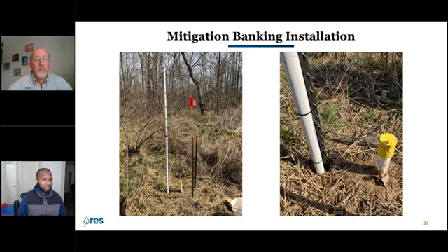So what we definitely recommend is to have some of those repeaters handy so that you can use them as a hopping mechanism to help ensure that the data gets back. I would say the strength of this system is around that redundancy, where you can provide multiple paths for the system to get back to that main hub.